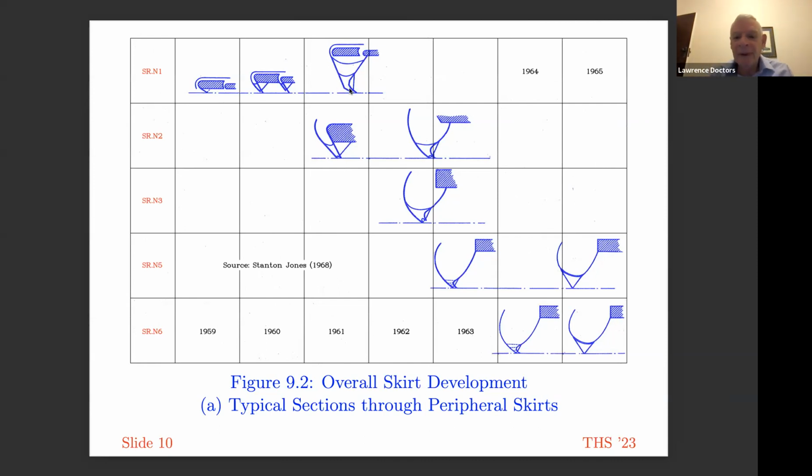The whole concept, of course, of the annular jet is just about disappeared when you go down to the bottom right-hand screen, where the skirt consists of a bag and fingers. Of course, the air is still going to leak out, as I'm showing with the pointer here. So you are going to get a stream of air like this, but not nearly like the original idea of an annular jet. Going back to the SRN1, you can see this complicated bracing. These are diaphragms inside the annular jet. That would have greatly increased the stiffness of the skirt, and that would be a fundamental problem with anything like